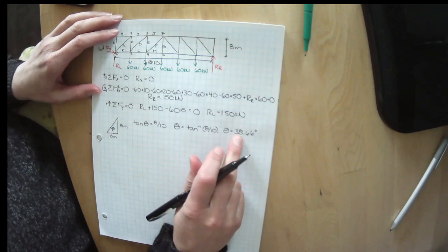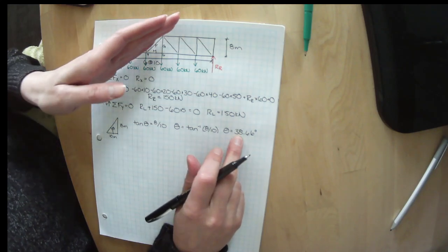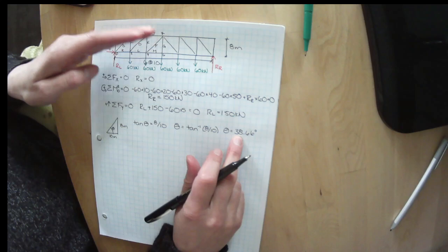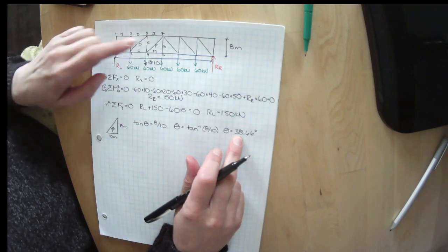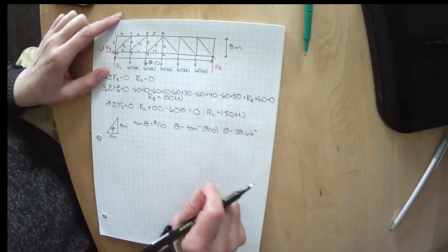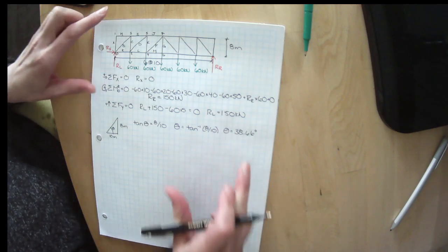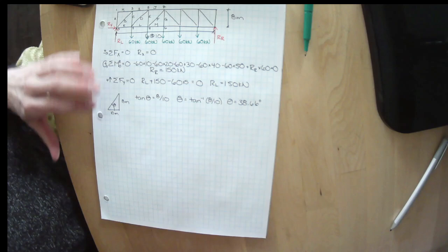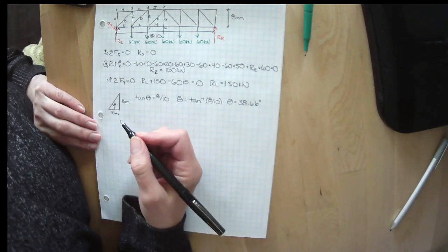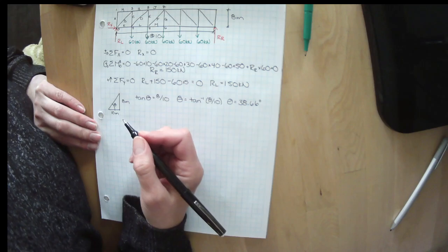So that means now going forward, whether we're talking about B, D, or F, the y component of the force will be the hypotenuse times the sine of the angle, and the x component will be the hypotenuse times the cosine of the angle, because we like to develop routines. Let's go through and start making our cuts.